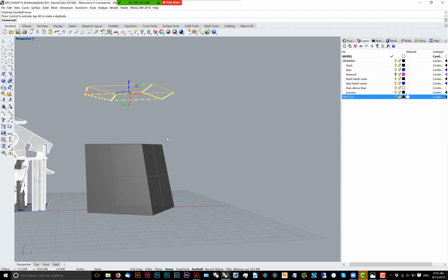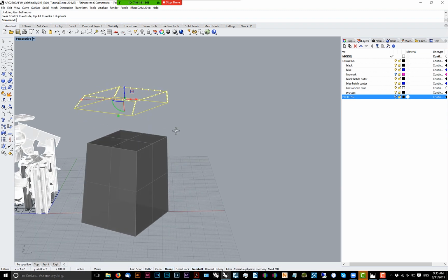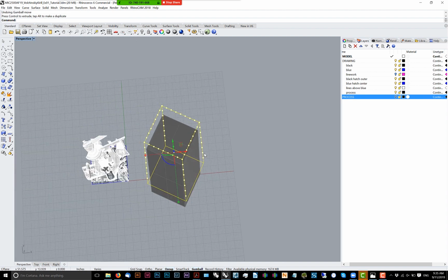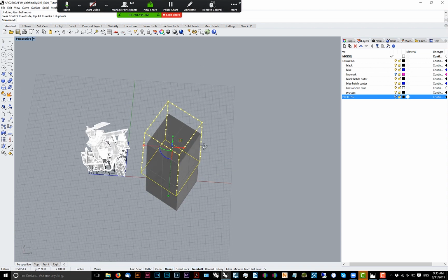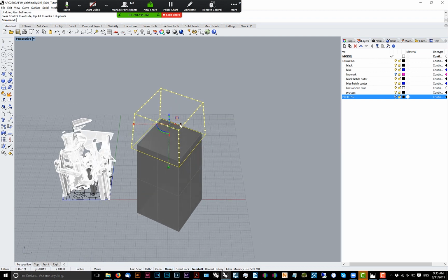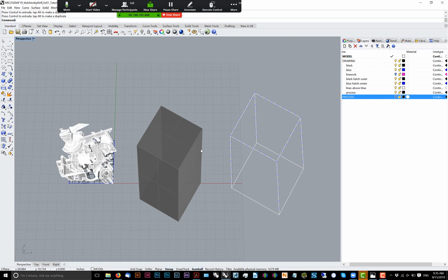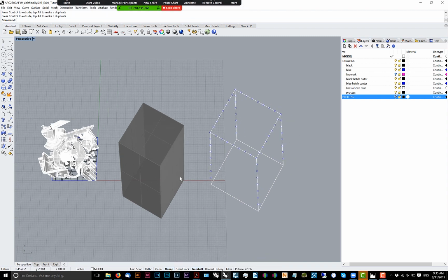So you can see the way Rhino works. All of your projections, you can use various techniques, but generally what you do is you use the top view and the C-plane to generate all of the readings of your geometry. So this is a result of basically translating the points and the lines from this geometry.